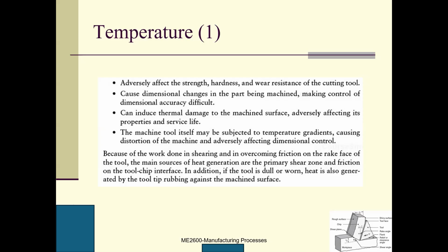However, if this material has very bad heat transfer properties, the heat cannot be dissipated into the neighborhood very quickly, so we will have thermal damage. It will cause substantial thermally induced strain deformation and will result in cracks. It's very bad.